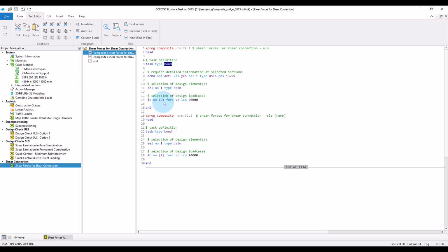You can see here that we first do the calculation for the ultimate limit state design load cases, superposed to give maximal and minimal shear force. As we have already used these load cases for the ultimate limit state design checks, we will store the new results for the uncracked section properties under different load cases, therefore using an offset for the result load cases, here for example 20,000.